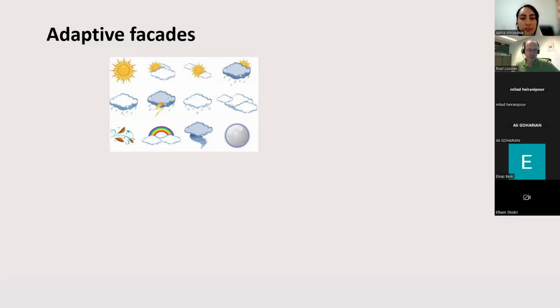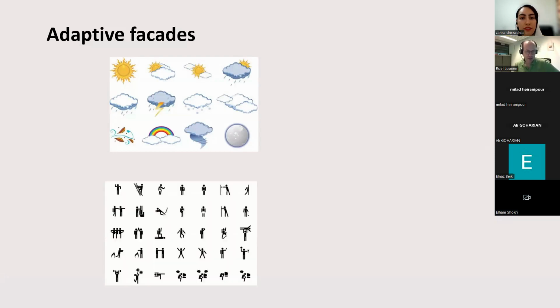On top of that, what happens on the inner side of the buildings, also we can have a large variety in terms of conditions. And now the argument is that if we can have the envelope to respond to this in a dynamic way, then we can over time adjust actually what is the optimal configuration to provide insulation in winter, to provide view to the outside when the occupant is there, but maybe to choose for protection during nighttime when there is no occupants in an office building, for example.